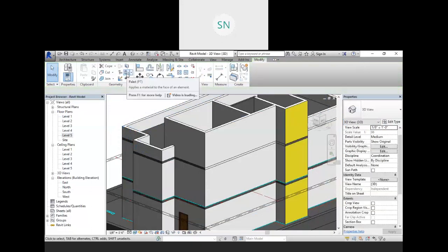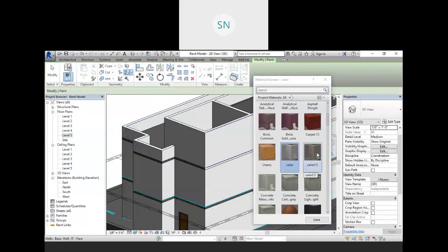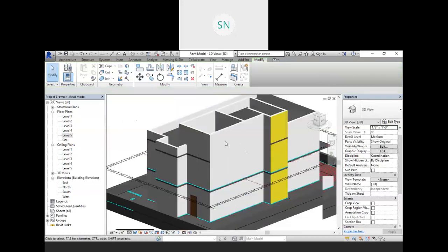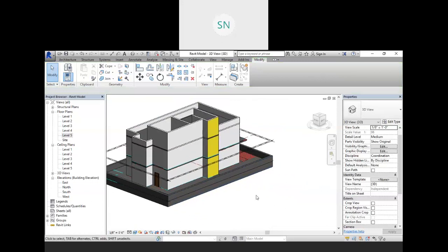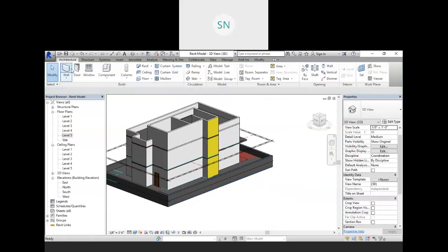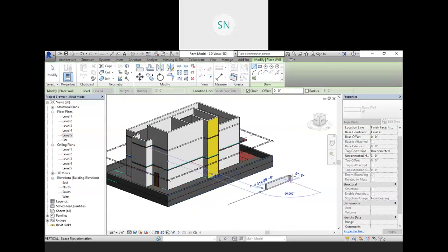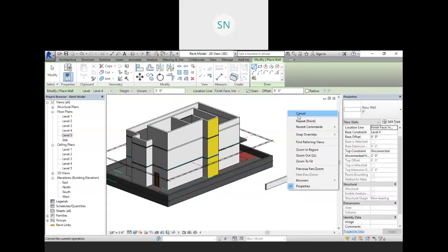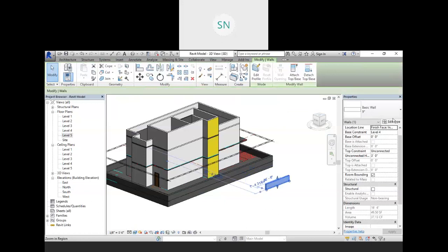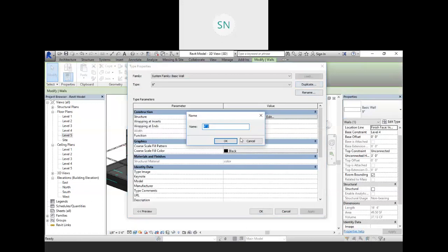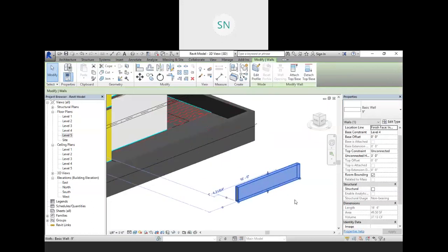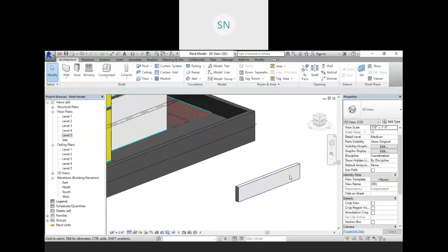Now if you go to the paint option, that new color will be there. So whatever colors you are creating, just apply on a single object. Or my personal suggestion to you, just create one extra object over here with an individual category. So click on this and click on duplicate and OK. Now to create material you can use this object to create only,